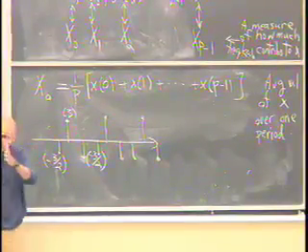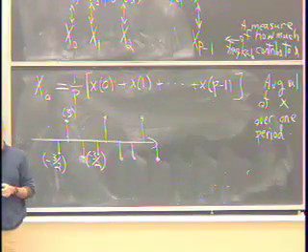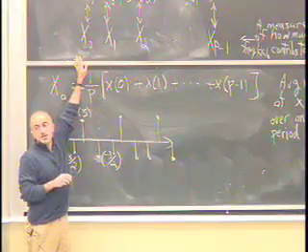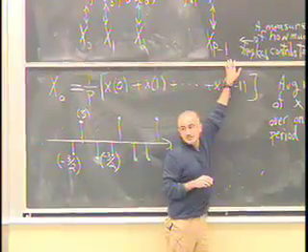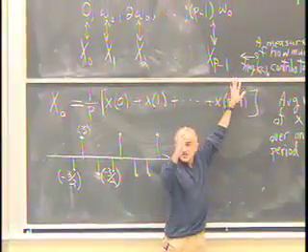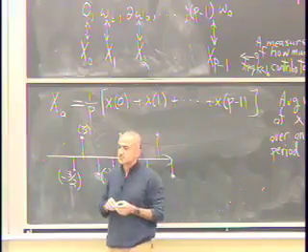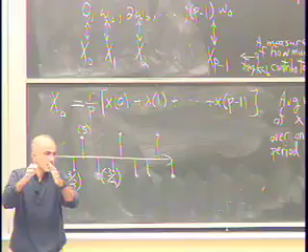Their magnitudes will tell you the contribution of each frequency to the signal. So if the magnitude of x0 is very large, and as you go up in the k index the magnitudes decrease, what kind of a signal is that? It's low pass. It's got most of its energy content around 0.